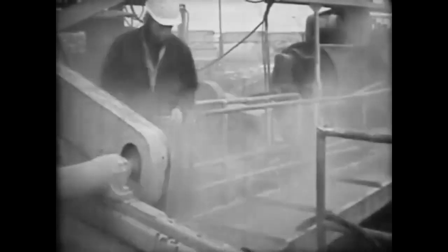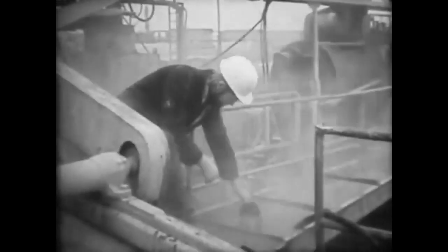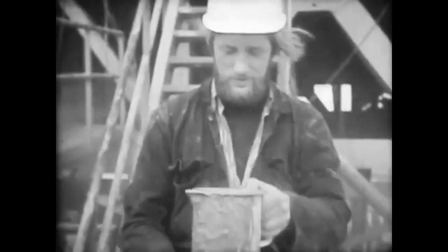As drilling goes on, the mud return shows the succession of different rock layers we're passing through. Some of them could contaminate the mud and prevent it from functioning properly, so we need to keep a constant check on its composition. The mud must also be maintained at a given viscosity and density. We don't want it altered too much by the rocks we're drilling through.